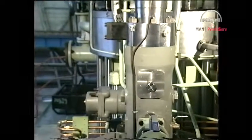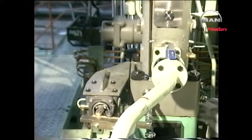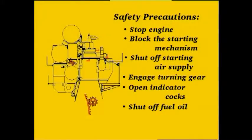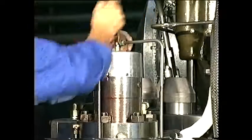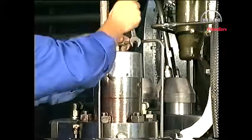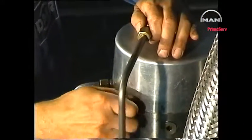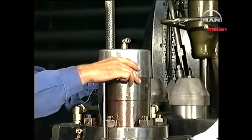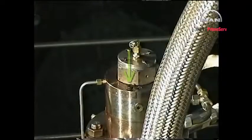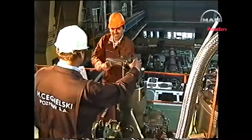Cams must be turned if the value calculated in step 1.4 of this film is exceeded. The actual fuel pump lead must be determined before turning the cams. Make sure that the reversing links are in the ahead position. Disconnect the air pipe and remove the cover from the puncture valve. Remove the plug screws to provide access for the measuring tool. Remove the puncture valve.